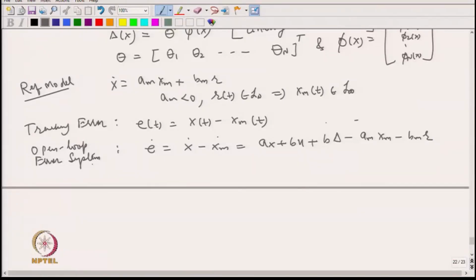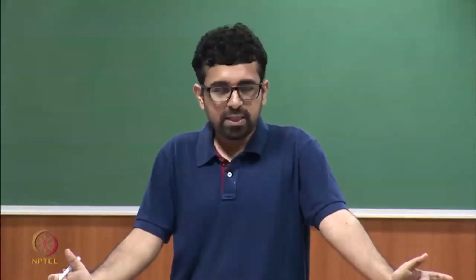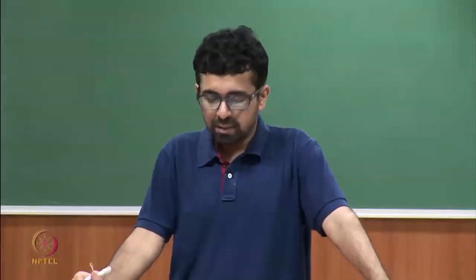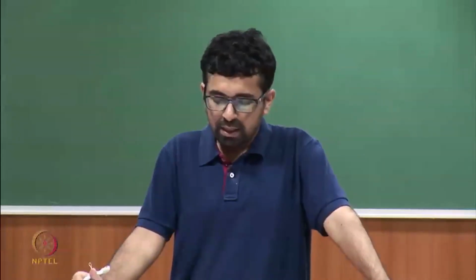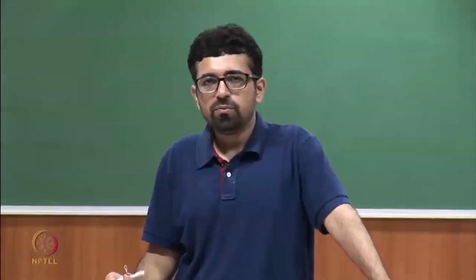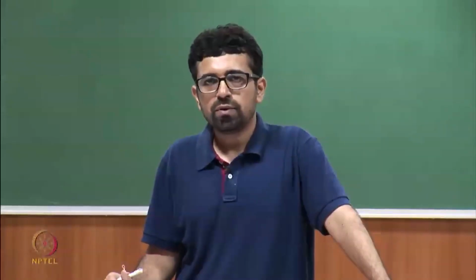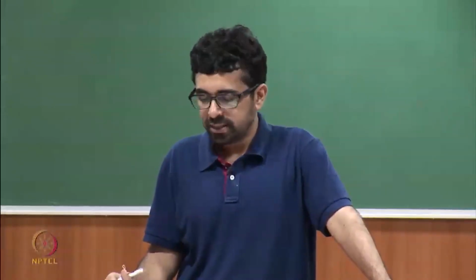The challenge here is how to design the controller U to stabilize the system. If the delta term wasn't there, we would go ahead and design the direct MRAC or the indirect MRAC case. Because there is a delta term, we would have to modify this controller, maybe add an extra term to account for this nonlinearity.